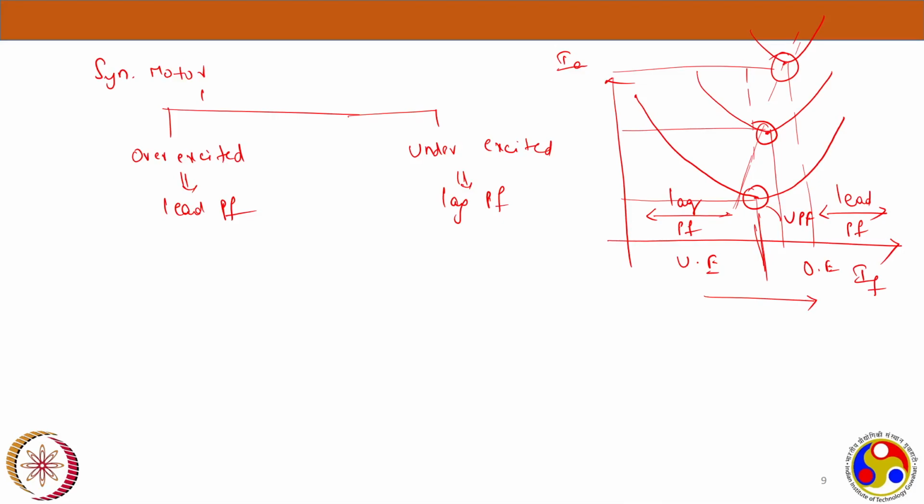So one application of this particular thing in the actual power systems is the synchronous condenser. This is a very nice property that our synchronous motors have. These are important points which I'm going to say now, so please listen carefully to how exactly we are applying it in the real world. Because of this property of the synchronous motor, we can use it to draw leading power factor current. Leading power factor is always what is important, because a lagging power factor is not desired.